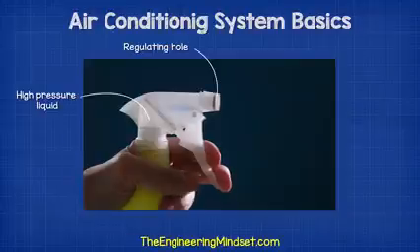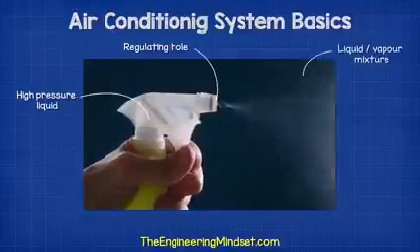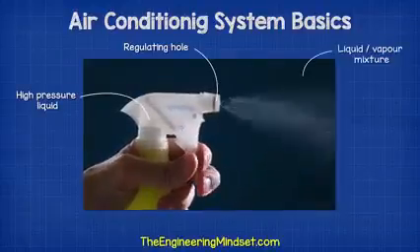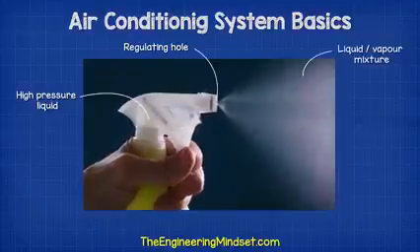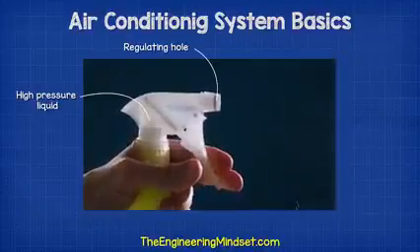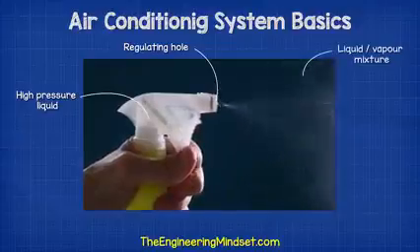It's a little bit like spraying a deodorant can or a spray paint can. It flows through a small hole, causing it to expand as a part vapor and part liquid mixture, and then we can feel the can become cooler.